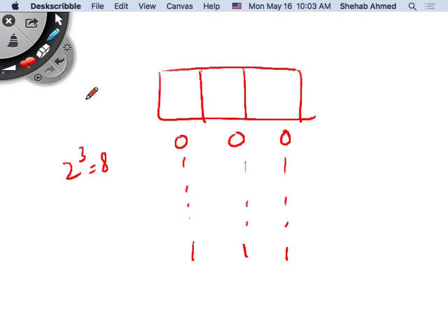So anyway, computers only understand, inside the computer, ones and zeros. First I have my sensor. For this sensor, I have to do some amplification stage, which is the core of our course. And then there's this computer here that only understands ones and zeros. Computers do not understand analog signals. They do not like to deal with analog signals. They like ones and zeros. So to move from this amplified conditioned signal to ones and zeros, you have to quantize your signal. It's called quantization of the signal.